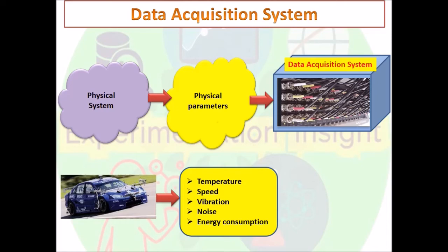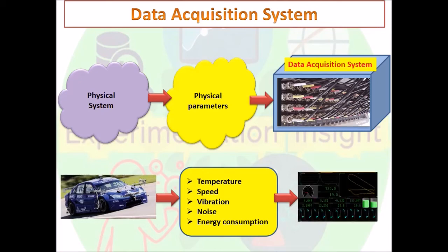If we want to validate the performance and durability of the vehicles, we need to dig down to part level. For example, take the engine. In the engine we need to measure several parameters such as engine speed, crank angle position and its corresponding instant pressure and temperature, and fuel consumption, and for an electric vehicle the energy consumption from the battery.